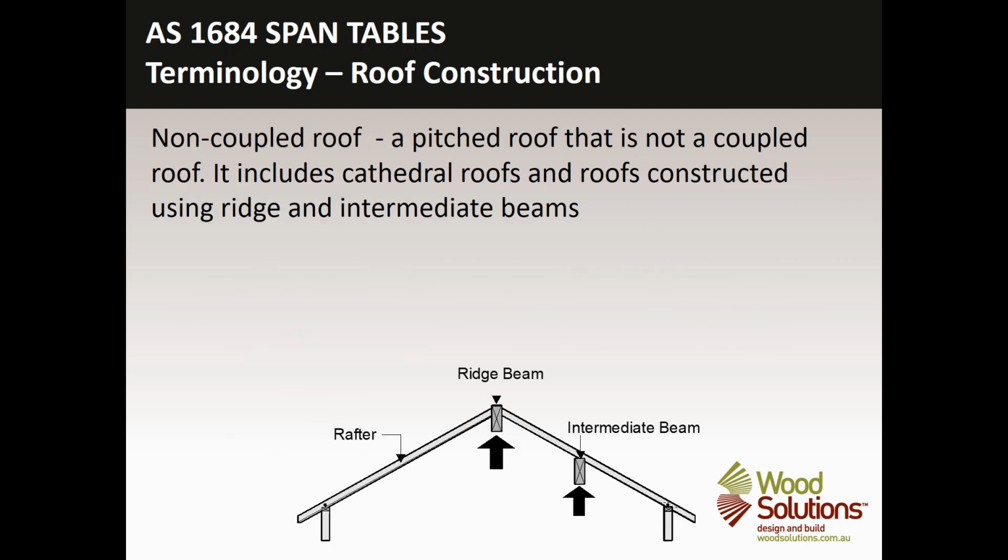Of course, we don't really want to go adding buttresses and flying buttresses to our standard dwellings. So we tie the roofs together with ceiling joists and collar ties. Another way of stopping that spreading is to support the rafters in an intermediate fashion. So back up to our church up here, we can have a large beam in the centre that runs from this wall through to the rear wall that supports those rafters. So as we can see on the slide here, a beam that runs all the way through the building that supports those rafters to stop them spreading.